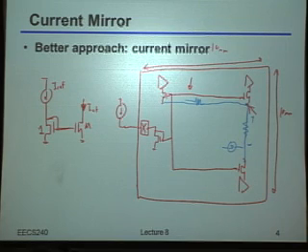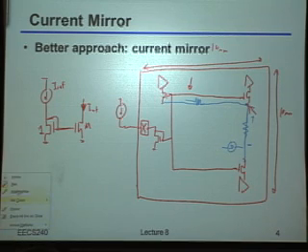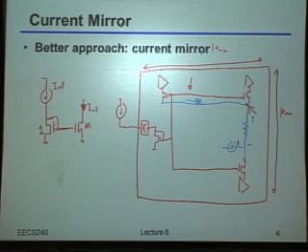Okay? Because unless it just so happens that there's the exact same current and the exact same resistance back to the external world from those ground paths, guess what? There will be indeed a voltage drop on the quote-unquote ground potential. Okay? So why is that really bad? Well, notice if this ground is different than that ground, what's going to happen to my VGS on those two transistors? Is it going to be the same, or is it going to change? It's going to change, right?